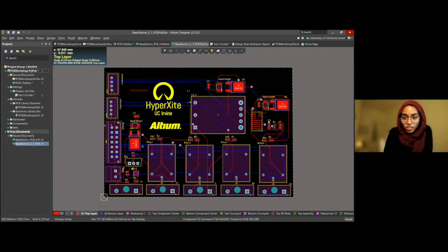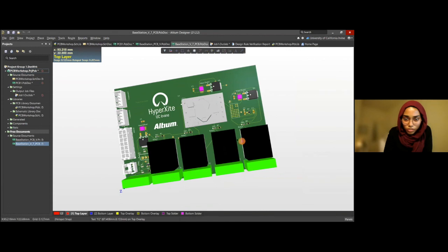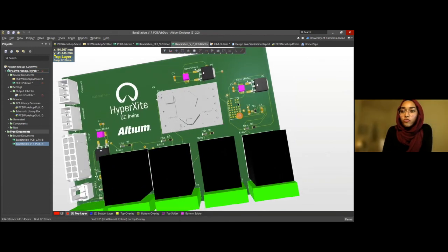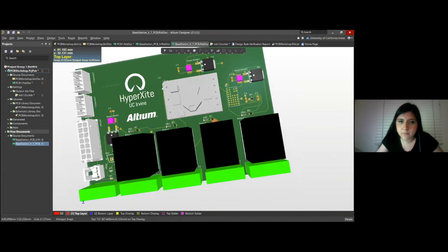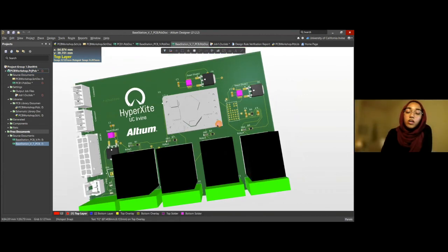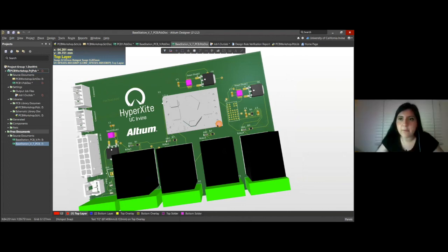And then there's this other component here with a bunch of little squares. I think that was another converter, but we found out that the ESP32 has its own DC to DC converter built in. And so we were able to eliminate a lot of these components and make things a lot more compact. Additionally, with the one we actually manufactured, we put 2 MCUs on it and put a lot of terminal blocks. So that means we would need more space to put in a Raspberry Pi, an ESP, and a good chunk of little green dudes.